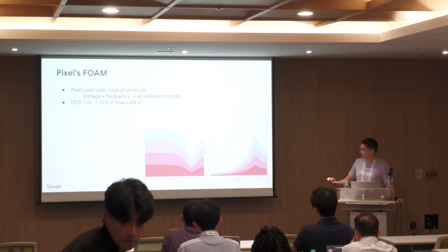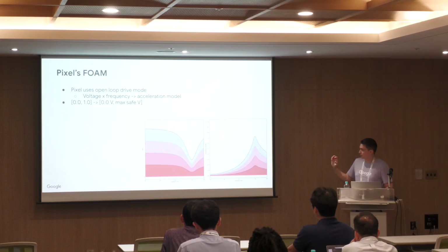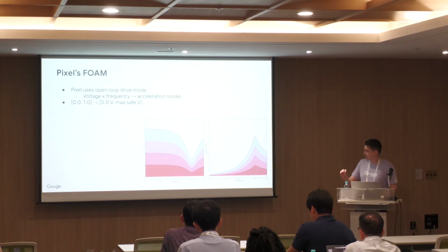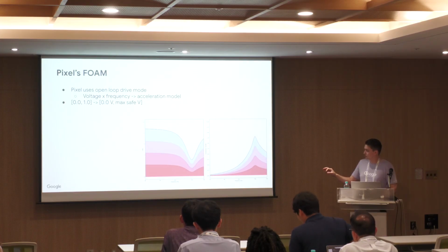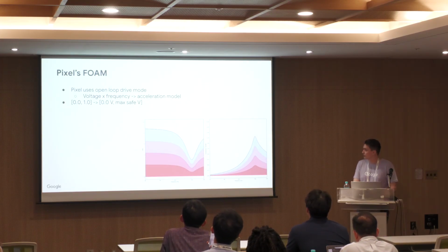This prevents amplitude distortion caused by our hardware output clamping the voltage down and playing a weaker effect than you might expect, or an effect with a different amplitude envelope than you'd expect, because it passes through a portion of the voltage limitation curve where the maximum voltage is lower than the previous point would be.